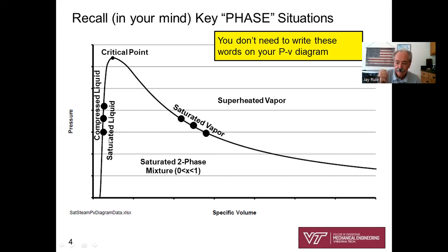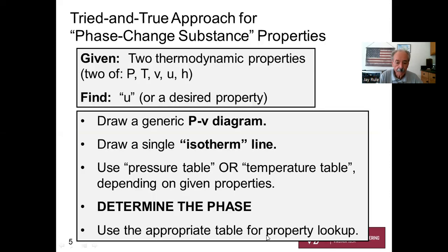It's liquid that's right at the boiling point temperature. It would be like really, really hot water. Okay. If you're to the left of the vapor dome, then you're a compressed liquid. And examples of that would be like tap water, shower water, warm water, boiler feed water. Those would be examples of compressed liquids. You can see all of those things with your eyes, of course. All right, that's going to be key in getting the assignment. What is the specific internal energy of your state, wherever you sit?